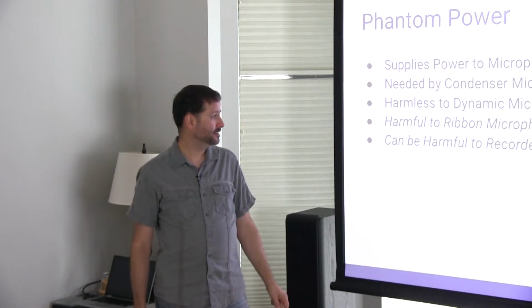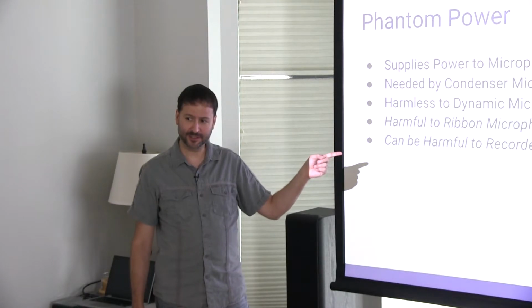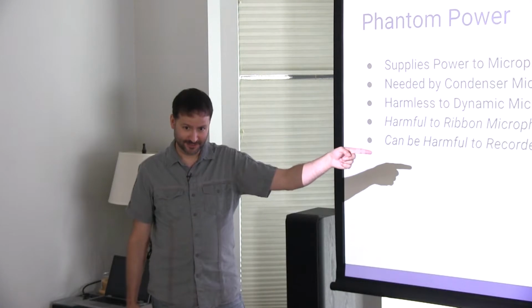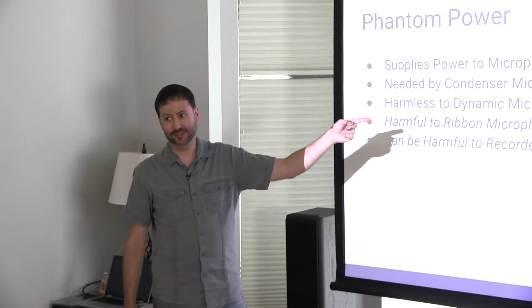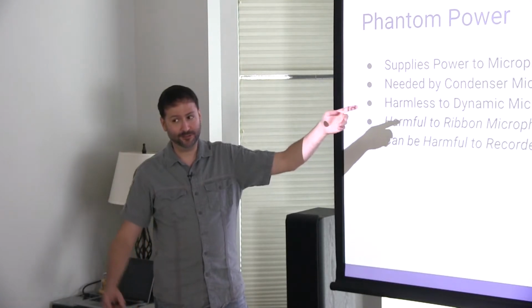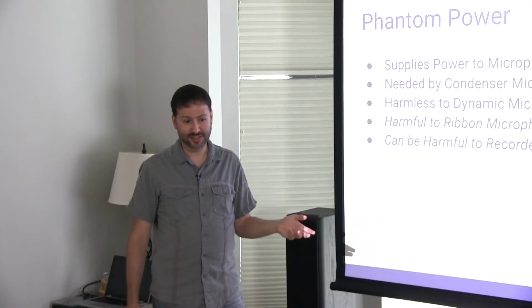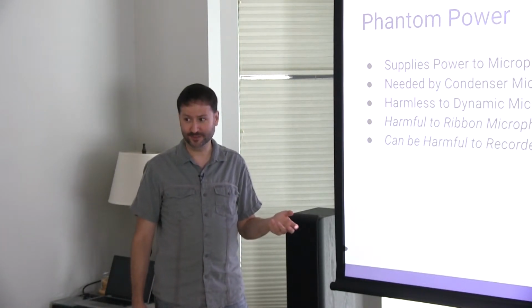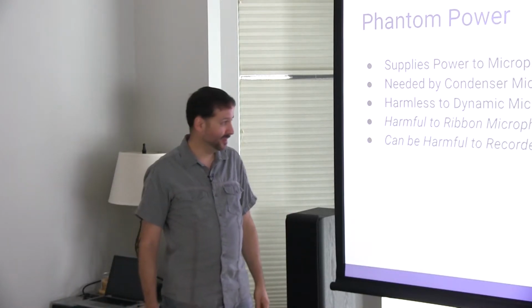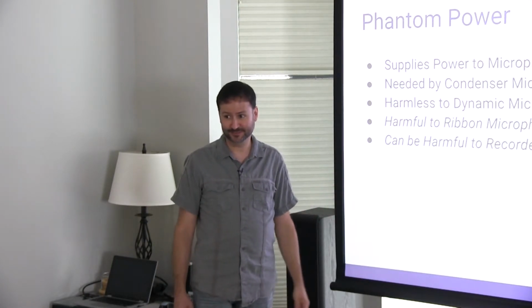And I have blown up a recorder by plugging it into a mixer and sending phantom power to the mixer, which the mixer didn't need, and it didn't like it. When I figured out that it was doing that, I turned it off and I was able to record. But after that, I had this whistle in my recorder, so I had to send it in to be fixed. I don't know for sure, but I think that's what caused it. I mean, it started right after that.